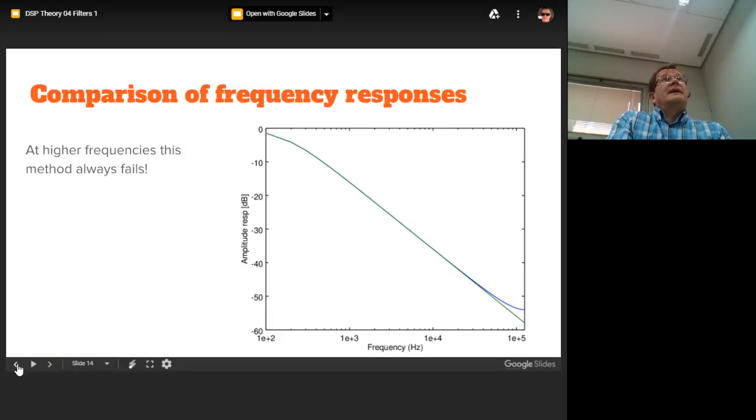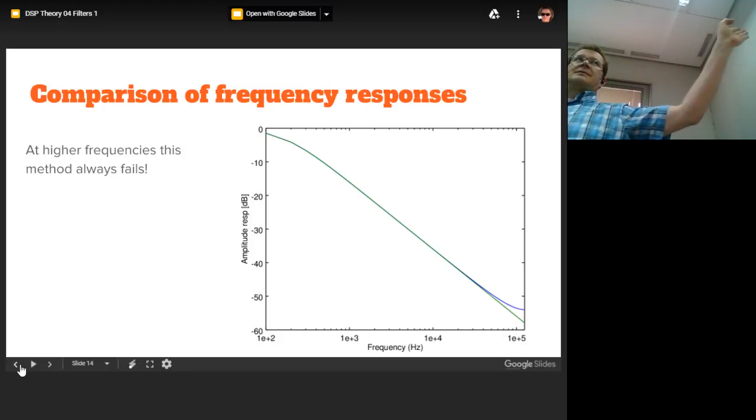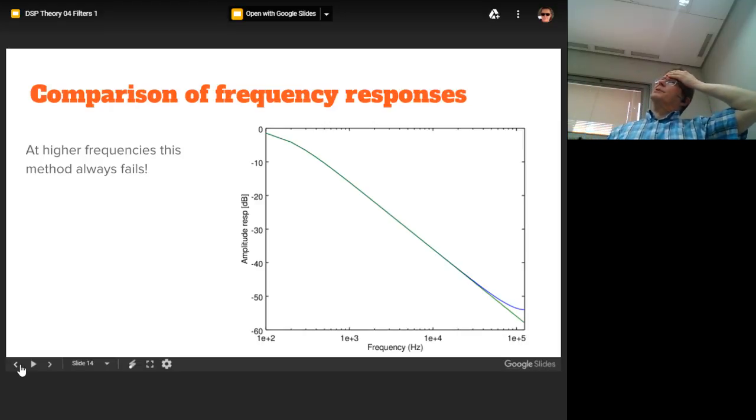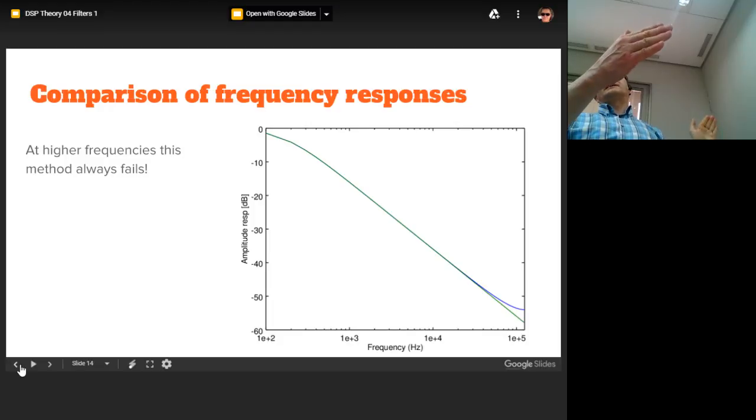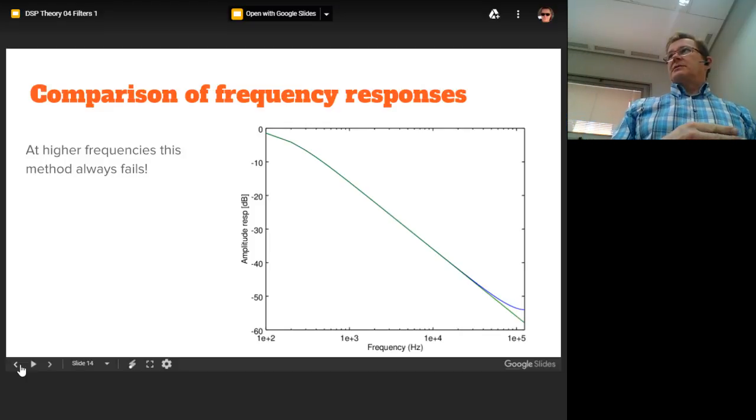Okay, and actually that one is a modeling of what happens if I didn't have any noise. Well, this is bound to fail because in the real world you always have those high spectral components, and it means that if you are taking samples of that kind of system, the higher spectral components are showing up as the alias spectrum.